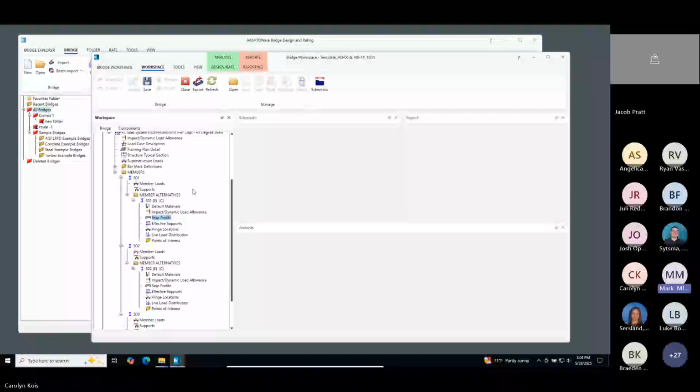Right, and if you basically have the same rebar spacing the whole way across, you're going to have a wider section, but it's going to be the same spacing, so it's going to give you roughly the same capacity. But as Carolyn said, when you get to the exterior of the bridge, you may have spacing that's closer together, and so you'll have a different relative capacity.